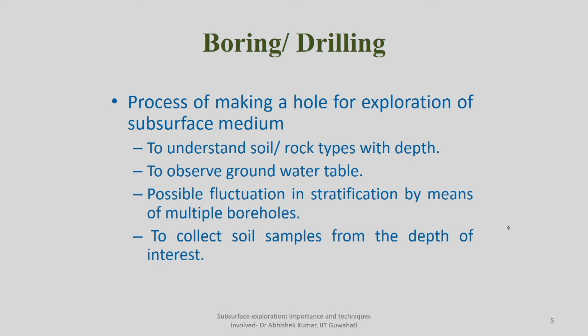Boring and drilling are particularly useful to understand what kind of soil there is, because, as I mentioned earlier, once you do the test, you will be able to collect the soil sample. Once you collect the soil sample, you will get to know what kind of soil it is. Similarly, in case of rock, what is the kind of rock available at different depths. It may or may not be possible that at a particular depth you will have only a soil sample or only a rock sample. It can be a combination of those two.